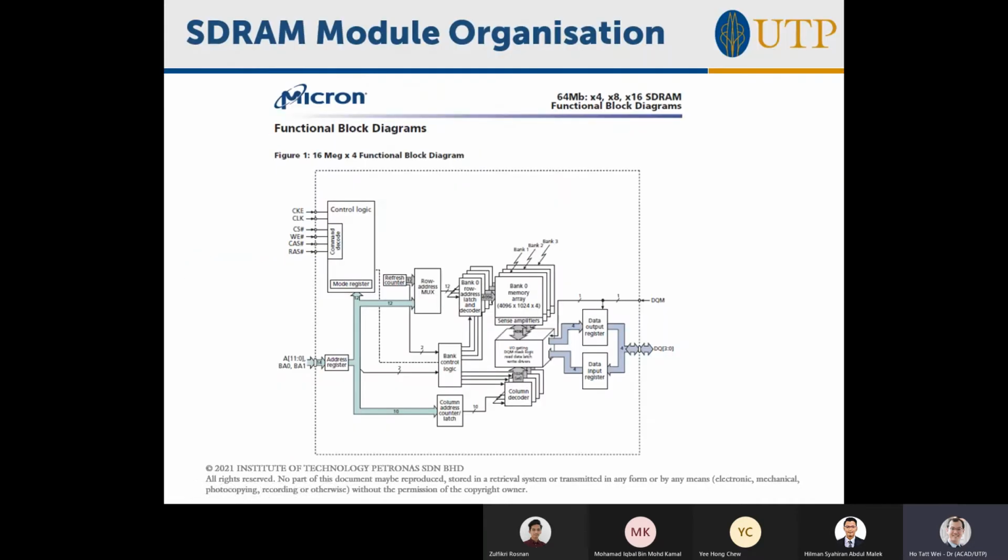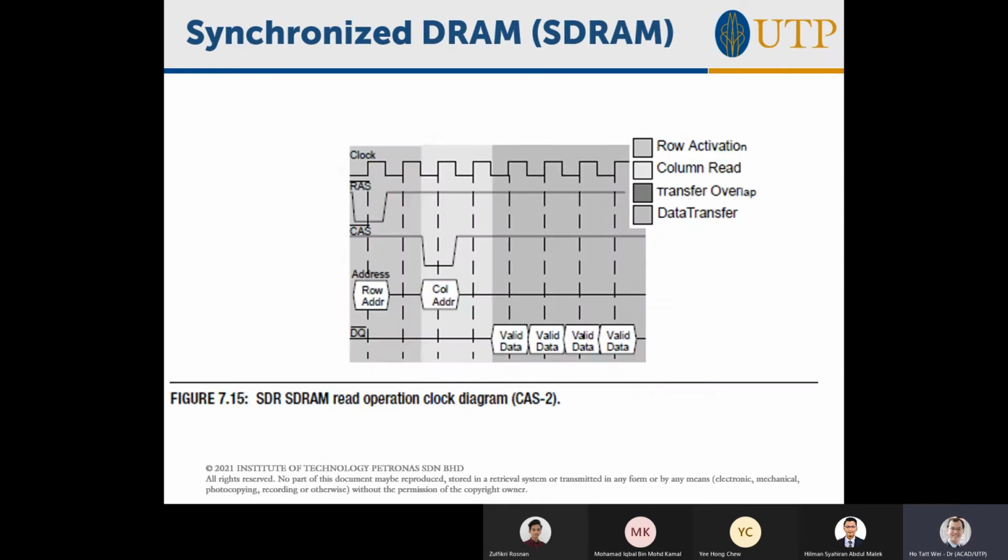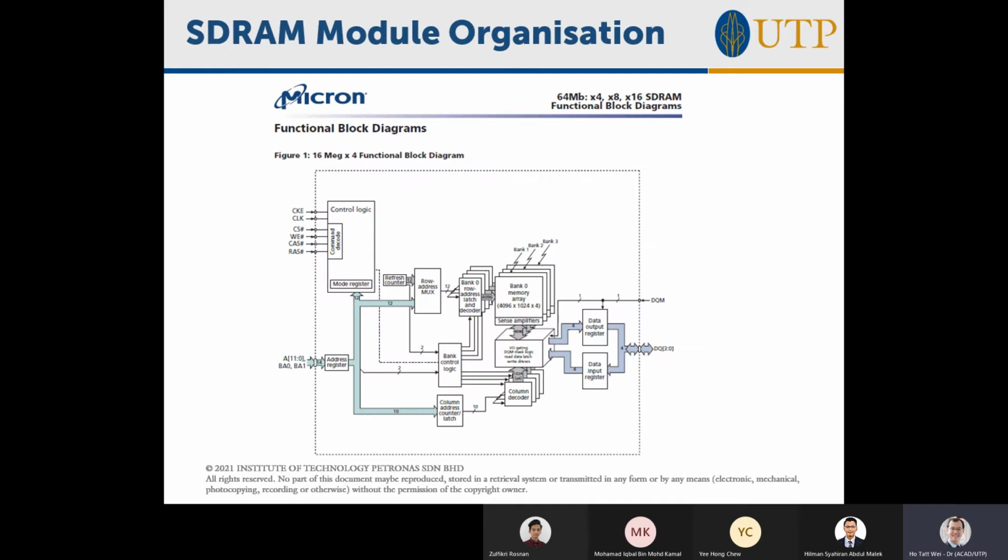Okay, now we're going to go to the second portion of the lecture. We covered the first portion, in which you now understand the basics of DRAM, what synchronous DRAM (SDRAM) is, and why it's a bit complicated to read it. It all comes back to the point that it's just one capacitor per bit, right? That is a key point. Why is it so challenging? It's because of the way it's organized. You have the row and the column select, and you're trying to get a very fast device. You have to do all these fancy things.